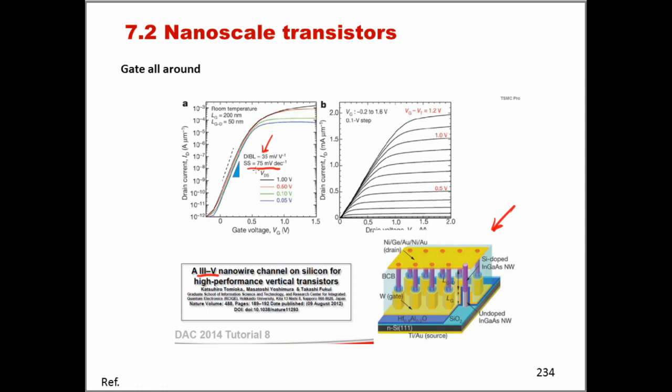That is, if you remember, if you apply voltage on the drain, you should expect, as a short channel effect, that there is some effect on the height of the barrier. So this number here is telling you that for each volt you apply on the drain, you should expect a lowering of the barrier in the channel by 35 millivolt.